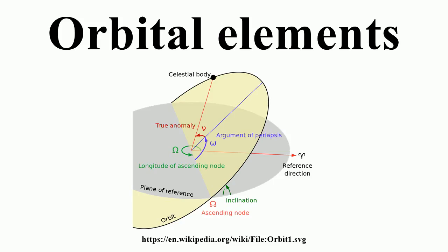Depending on the application and object orbit, the data derived from TLEs older than 30 days can become unreliable. Orbital positions can be calculated from TLEs through the SGP, SGP4, SDP4, SGP8, SDP8 algorithms. Example of a two-line element.